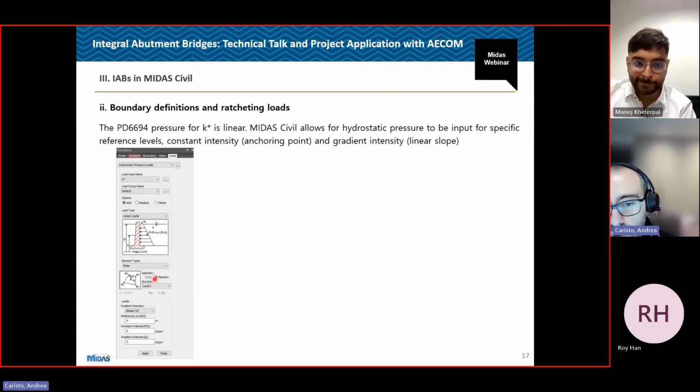The local direction of the plate, z, will be the in or out from the plate, so top, bottom. The minus or plus will depend on your local axis on the plate. So look at them and you will realize whether you have to put it as plus z or minus z. And this will give you the sign of your pressure load. The gradient goes in global Z. What it means is that global Z minus, sorry, what it means is that I'm starting from the top of the wall and I'm going down in my case, because Z is pointing upward.